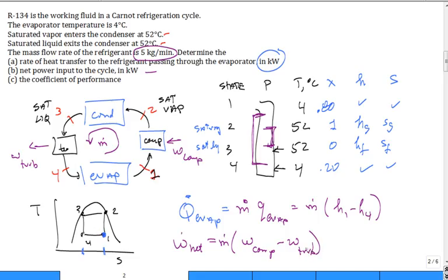And then those W's are both related to delta H's. And then last, what is the coefficient of performance for that refrigeration heat cycle? Make 2 calculations. Make sure that you calculate it using the simple equation, which is the temperature low divided by temperature high minus temperature low.